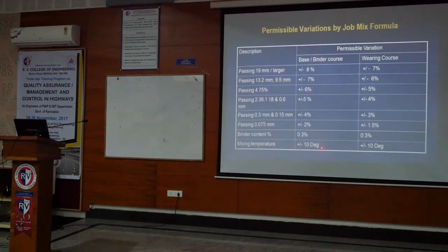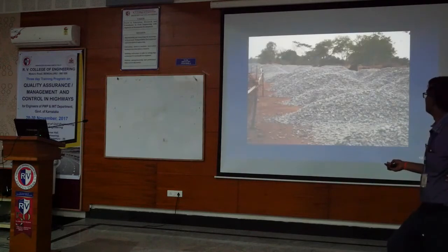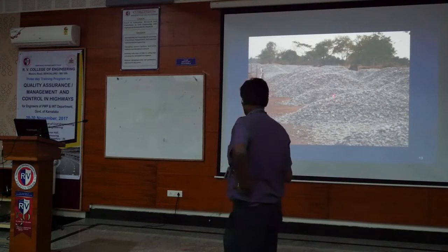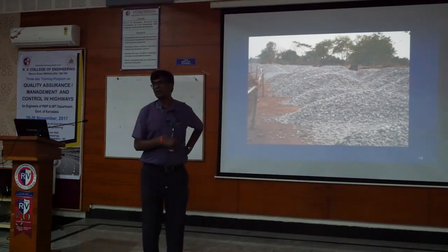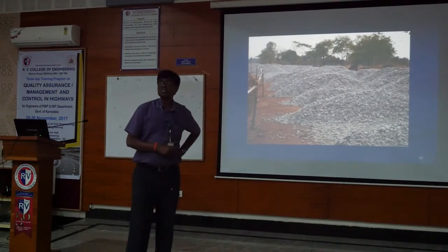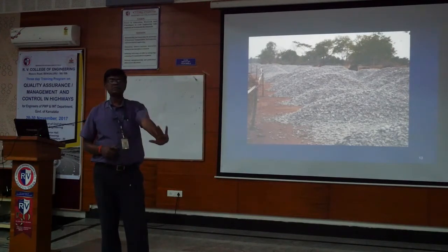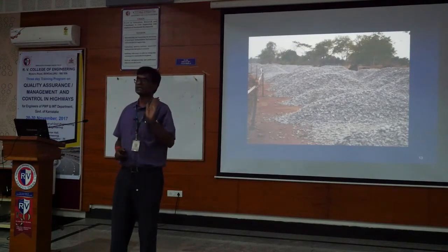When it comes to the temperature, it is plus or minus 10 tolerance. And this is not a good practice: stacking wet mix macadam heaps. That's not good practice. Ideally speaking, wet mix macadam is to be paved. That is the right practice.